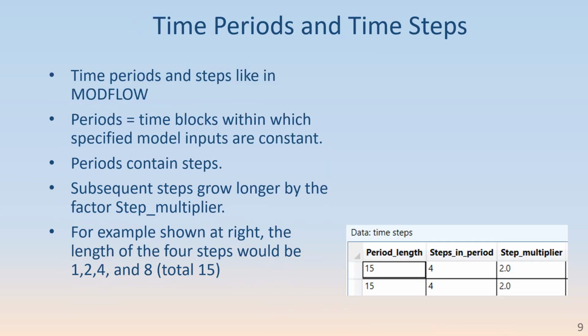Anaqsim makes use of time periods and time steps in much the same way as is done in ModFlow. Periods are larger blocks of time within which there are time steps, and the time periods define times when the specified model inputs remain constant. And you can make the subsequent steps during a time period grow longer by a factor called step multiplier.